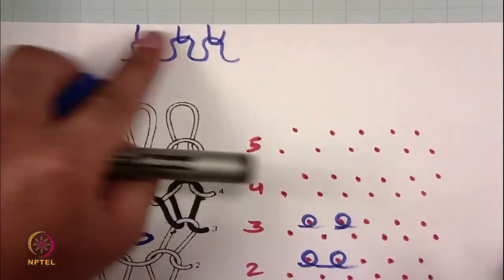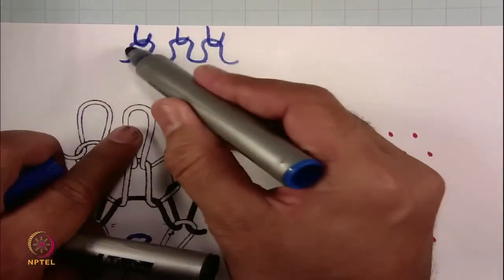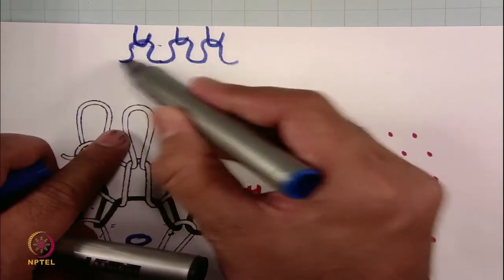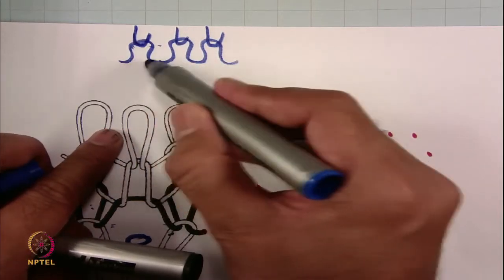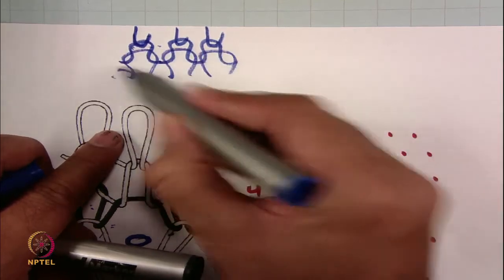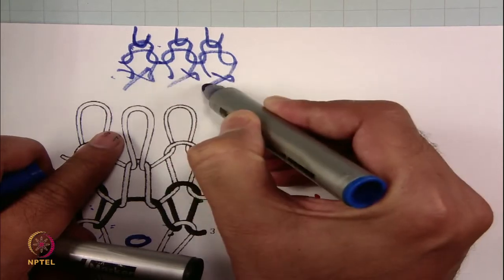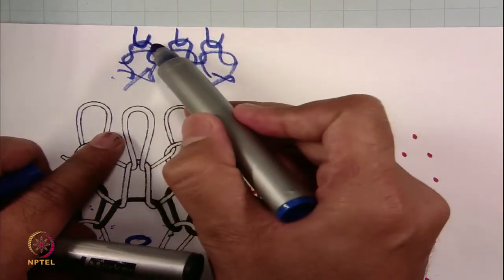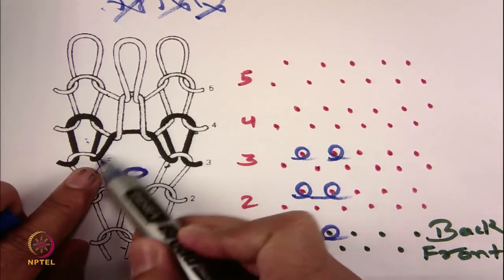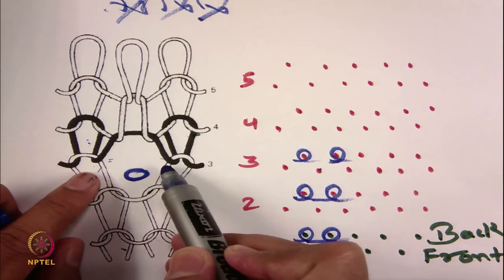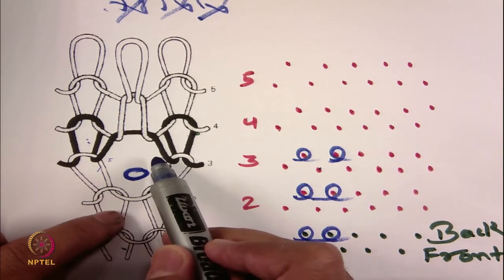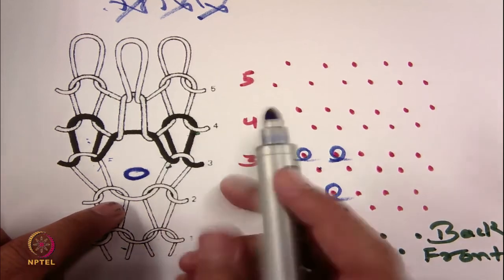Whenever the needle is pulling the yarn the first time, it will only create the needle segment, it will not create the other 2 intermeshing points there, because there is no old loop. So, this loop is missing. Because of that there are only 2 intermeshing points. Although if you follow the yarn movement, it looks like a tuck, since it is the first course or first loop on the front needle, 2 intermeshing points are missing.